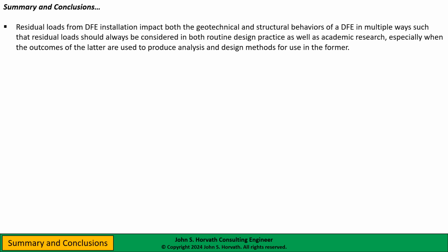And this goes back to what I said earlier, that I think a lot of the analytical methods we use in design practice, the shaft estimates are too small or too large, and the toe resistant estimates are too small.